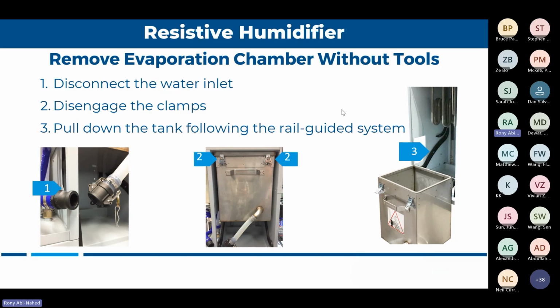Now, most of the time, if your water quality is fine enough, and when I say fine enough, it's less than 10 grains of hardness, all the scale on this heater will fall inside the tank by expansion and contraction. So anytime the unit stops to drain and then refills, the scale will fall off the heater and into the tank. So you don't really need to clean the scale on the heater.